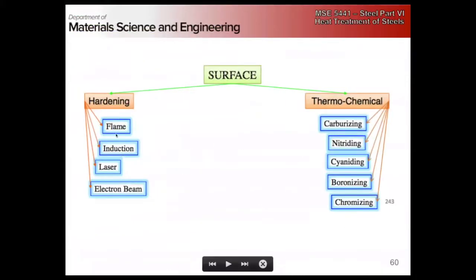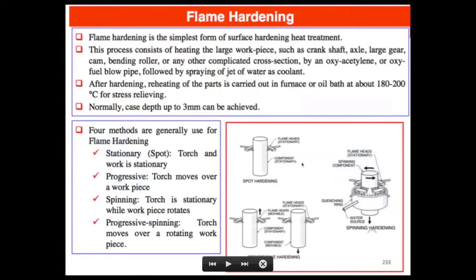And so these are essentially flame hardening mechanisms or thermochemical treatments. They both often lead to localized hardening at the surface. This tends to have to do more with carbon, and this with other elements, right, being the primary.